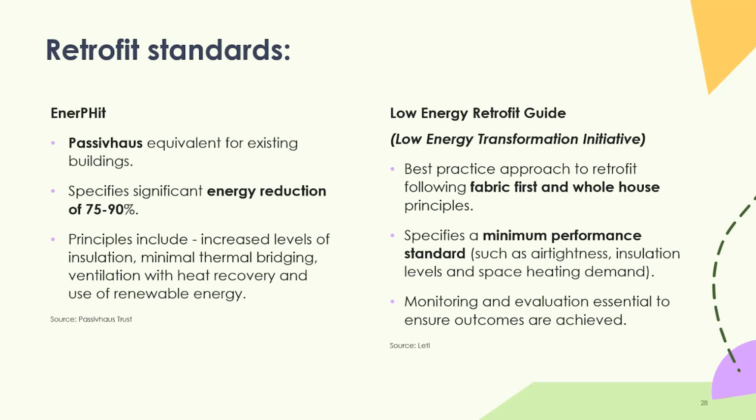Normally the question is, how far should I improve the fabric of the building to take me to a position where I can then decarbonize the heating without putting someone in fuel poverty? That's basically the big tension in retrofit, because obviously you want to get the home to a point where you can run that heat pump or something at a level at which it is not adding to the cost of running the home.